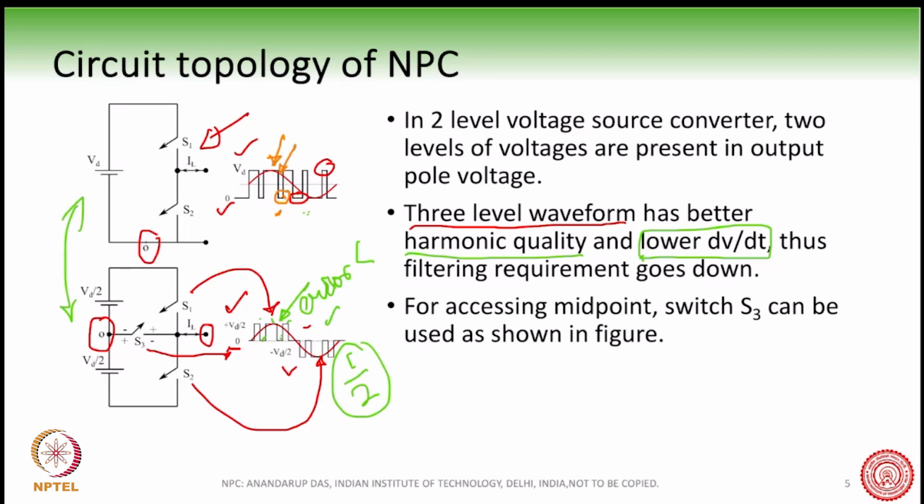So the lower waveform has lowered dVdt, which helps in motor applications. dVdt causes extra currents and wave reflection at the motor terminals. So therefore, this waveform is better.